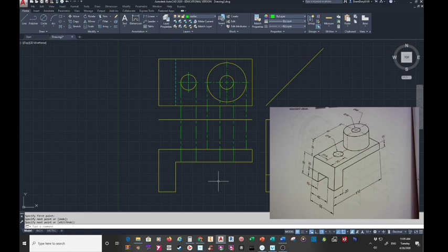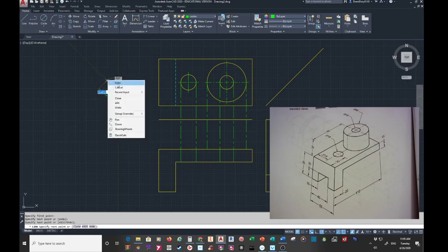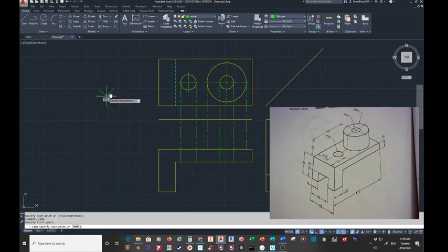So just remember that, and it'll help you out in the future. There would be a note that has a little depth symbol that kind of looks like this. Okay, and then it would have a number after it, and that would be after the diameter of your circle for this hole.